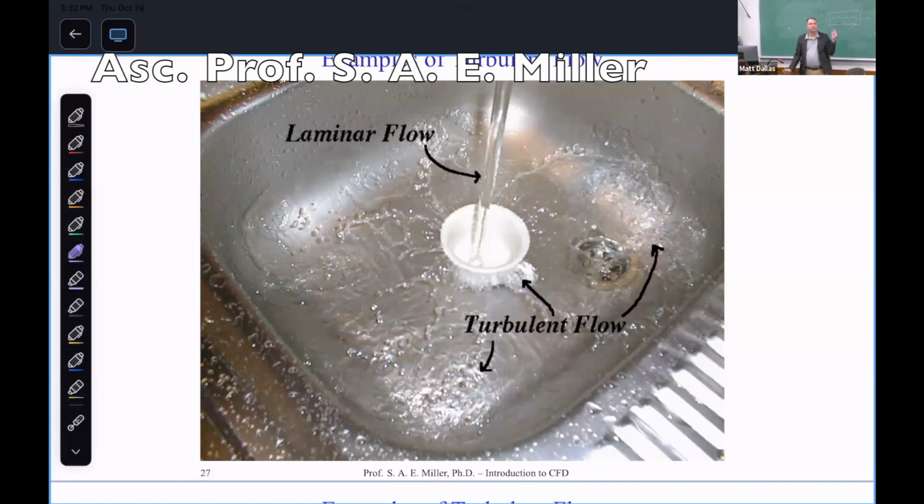It's laminar. It's clear. They call it laminar flow, these streamlines of the flow, like a laminate desk. They're just perfectly aligned, and the water just goes over each other. Laminar, think of a laminate desk. That's how I remember it. If I increase the water flow a little bit, all of a sudden it starts getting wiggles in it. That's transitioning to turbulence, just like in a pipe. Exact same type of instability in the flow. It's unstable. If I increase the water flow high enough, then this water jet will become turbulent. Also try this with a hose or something. And this is the basic way you can see transition to turbulence in your lives.